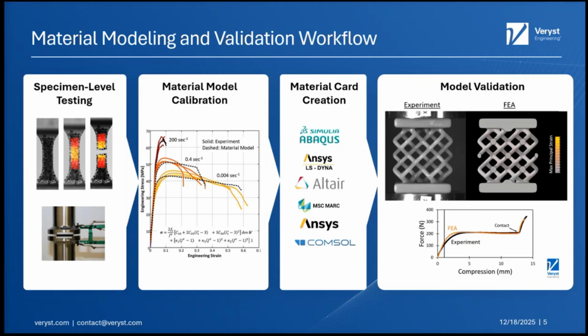The part that it could be an issue is when you talk about how that was made. So, if you injection mold something very, very thin, you can get a lot of built-in shear stresses and a lot of polymer chain alignment, and that could change your yield stress or your stiffness. Or if you have a different manufacturing process, that can too.